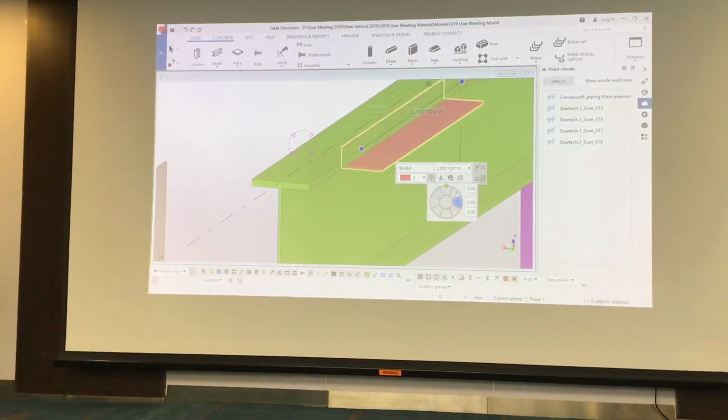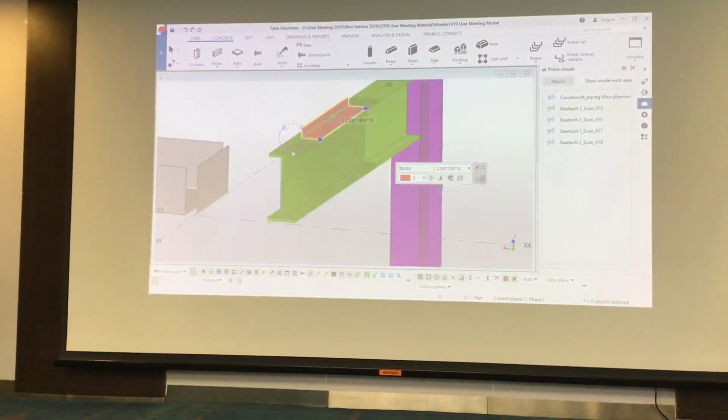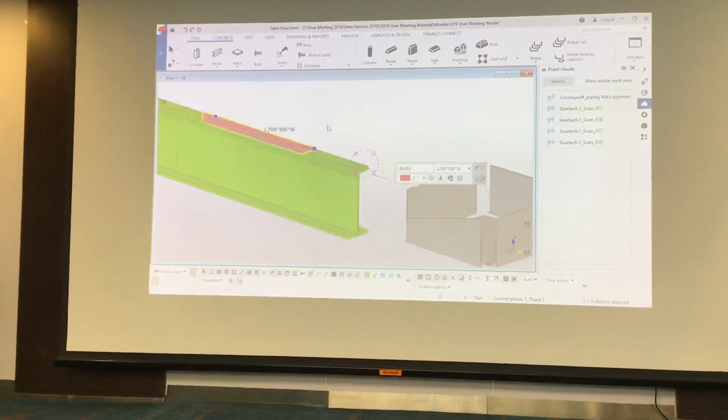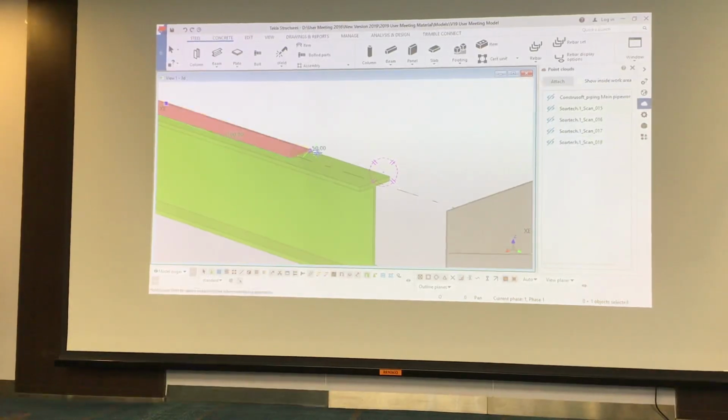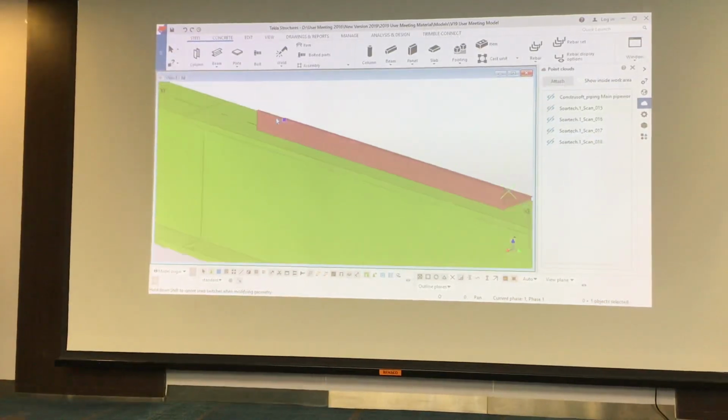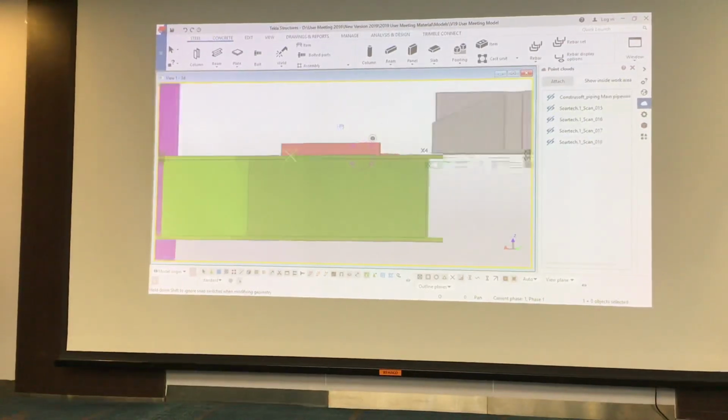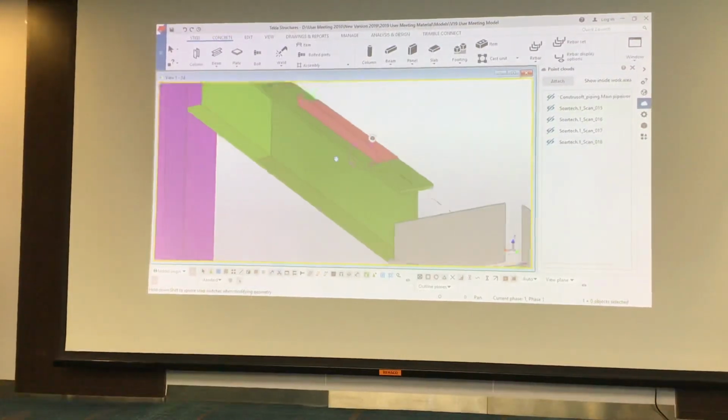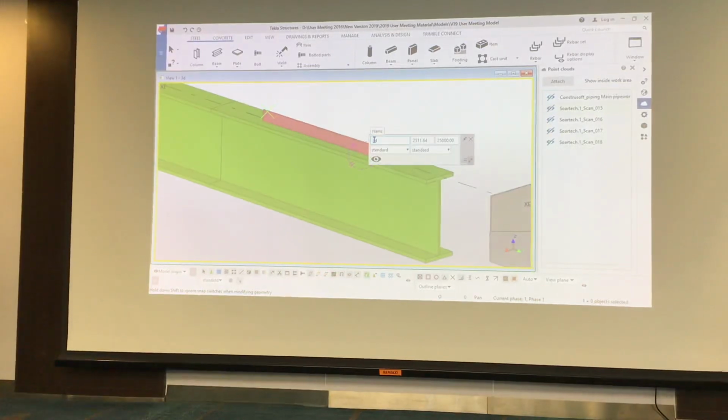See? You see how easy that is to work and use that within Tekla, like so. Right? To change the length of that now, you can simply pick on that and drag it another 150 millimeters. This one here, 150. And that's how you'd use those tools within Tekla. If you're not using this toolbar, it now works for everything, even on drawings. It's one of the most important tools we introduced, and most people do not use it.